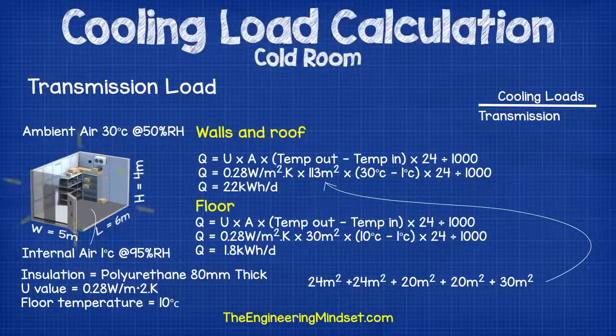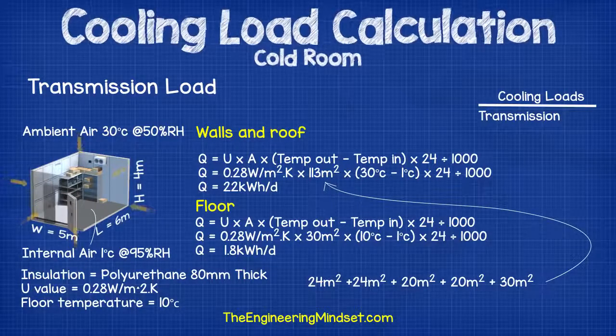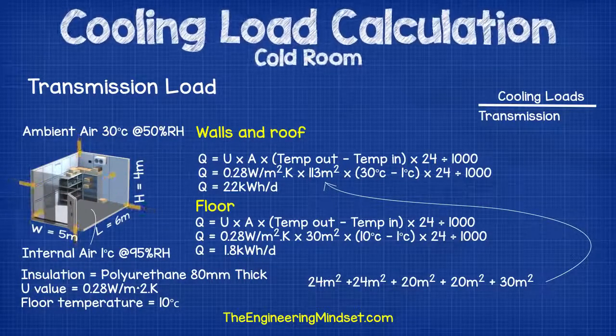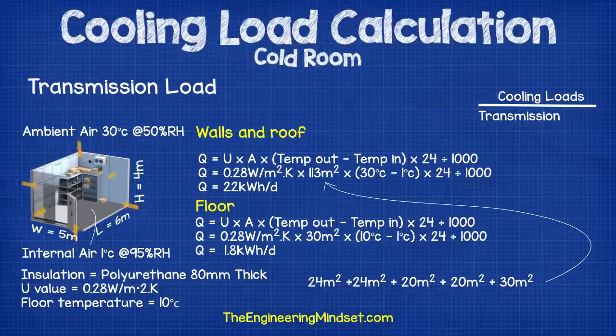You'll need to calculate the floor separately from the walls and the roof, as the temperature difference is different under the floor, so the heat transfer will therefore also be different. If the floor isn't insulated, then you will need to use a different formula based on empirical data.